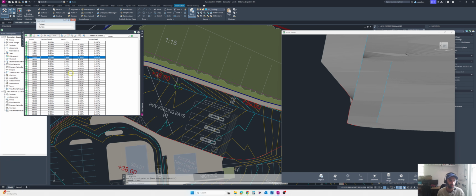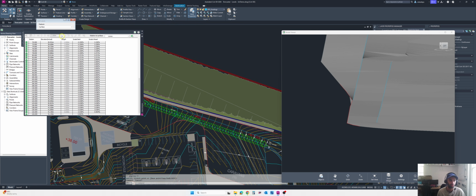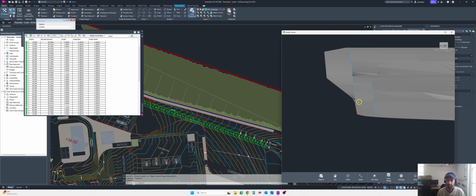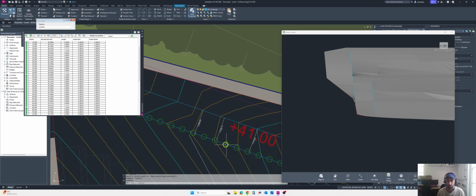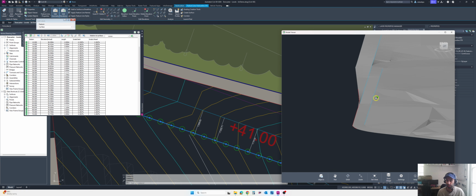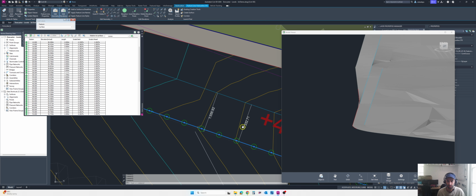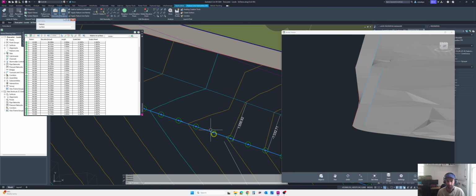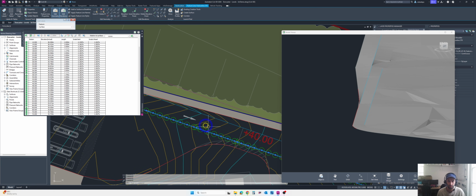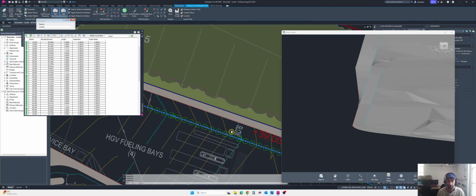I think so, yeah, 38.385, and goes all the way to this one and then change to constant grade, and this will help to see. And also add this feature line to model viewer. Yeah, this is already we have. So now we can see 5.66 quite slope. It is quite a level ground. So this is how I usually do the grading, and it will go one by one